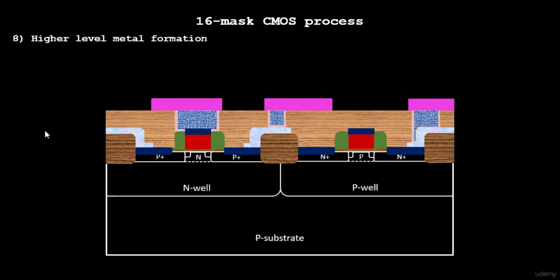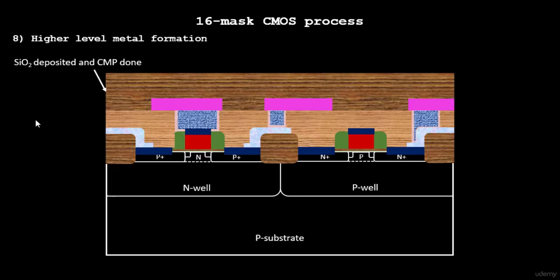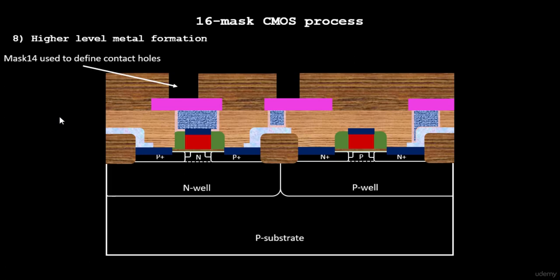Similarly, you have to decide which kind of connections can be done locally, and those connections are done using the TiSi2 that you have over here. For the connections that you want to bring to the top, you can use the next level of metal, which is TiN. This level of contact can be used to bring the bottom connections right to the top. So let's try to do that.